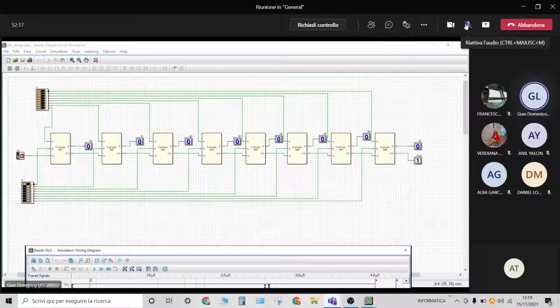This addition gives rise to a carry equal to 1, that goes to add to the second sum. The second one generates a third carry that adds to the third sum, and so on. So all the full adders generate a carry bit that propagates to the subsequent full adders and generates the maximum delay from the beginning to the end.